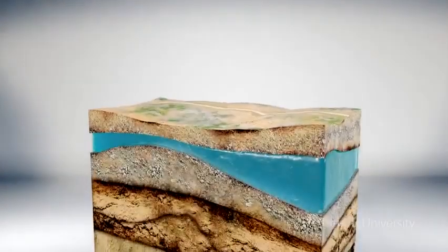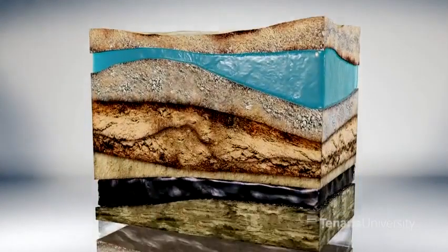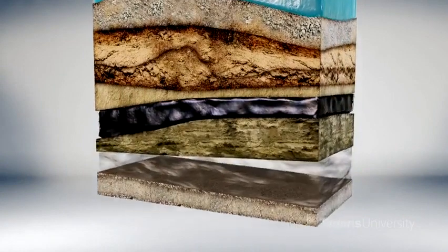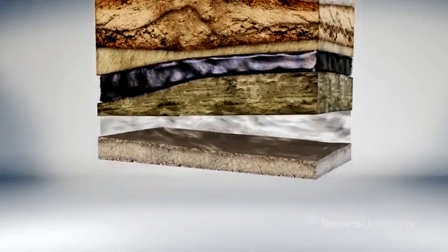Let's imagine that we want to drill a well from the surface down to 15,000 feet. Under the ground, we can find several layers with different characteristics and different properties, which make it practically impossible to reach the full depth of the well in only one shot. Hence, to achieve the final depth of the well, we need to drill by sections. And after having drilled each section, we must isolate and protect them.